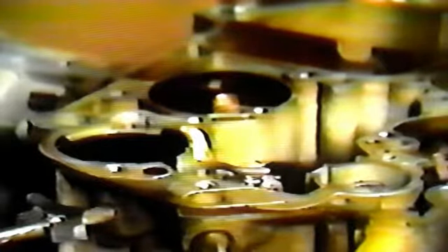an accurate float level. One special service tip we'd like to mention is that if you live in generally hot climates, you'll sometimes want to set the float at 1/32 of an inch under factory specs to help offset hot starting conditions. With the float back in place, you can now put the rest of the carburetor back together and